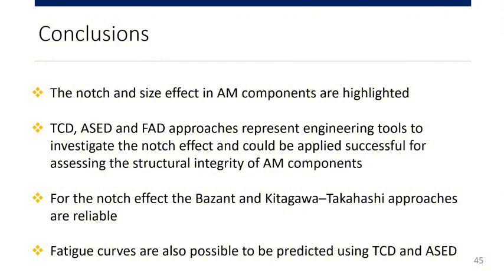And this is a good point, that we can conclude that we can apply this even for these additive manufactured components. I know there are some results on applying the SED for metallic additive manufactured components. The notch effect approaches are also reliable. Kitagawa-Takahashi could be used. And I didn't put it here, but we have also predicted the fatigue curves using the average strain energy density for the same combination, PLA and PLA reinforced with carbon fibers, and it looks good also for the fatigue predictions.